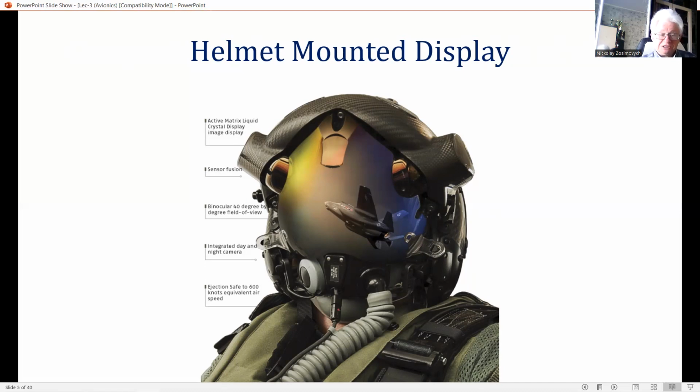Attitude information is referenced to his line of sight, LOS. The HMD can also have a wide FOV ranging from 35 to 40 degrees for a fighter aircraft application, to over 50 degrees for a helicopter application.